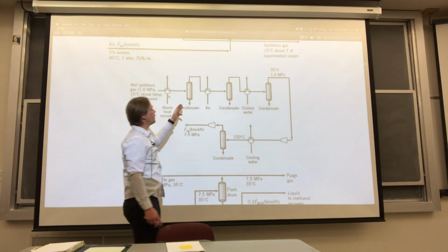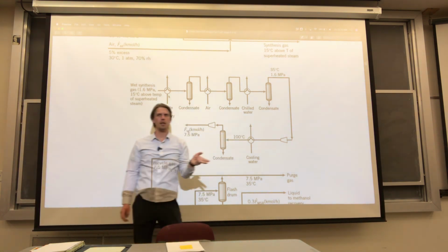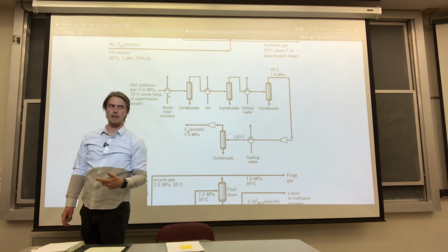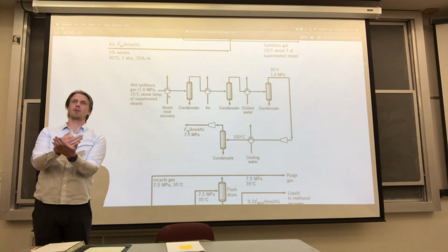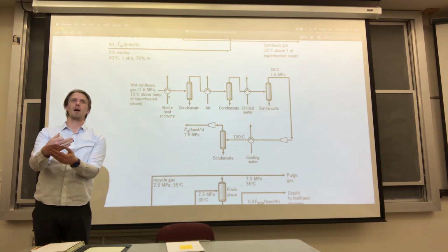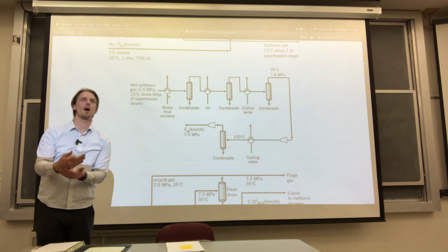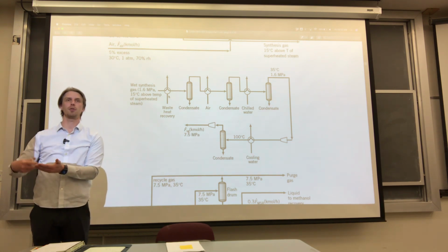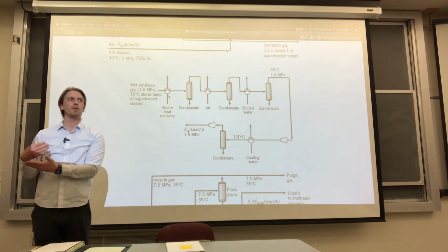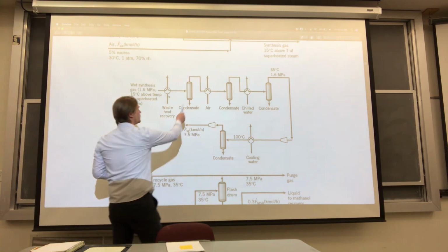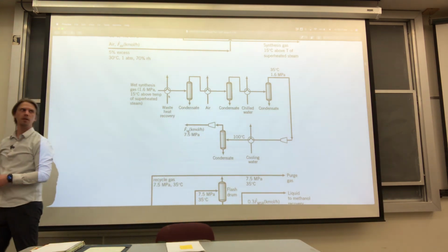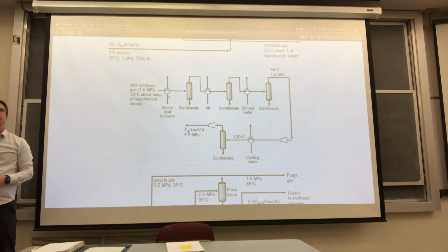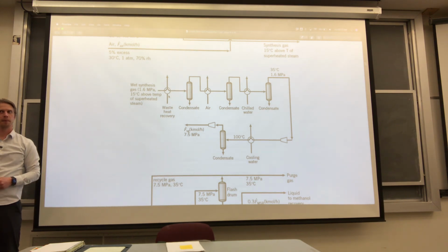Let's say we are removing 1/3 of the water in each of these different condensers. So what that requires you to do now is to do a material balance and then figure out at that mole fraction of water, what is the saturation temperature going to be, where you can use the steam tables or Antoine's to figure that out. And then you have to balance each of these three condensers with a phase transition energy balance. So not a reactor balance on this particular one here.